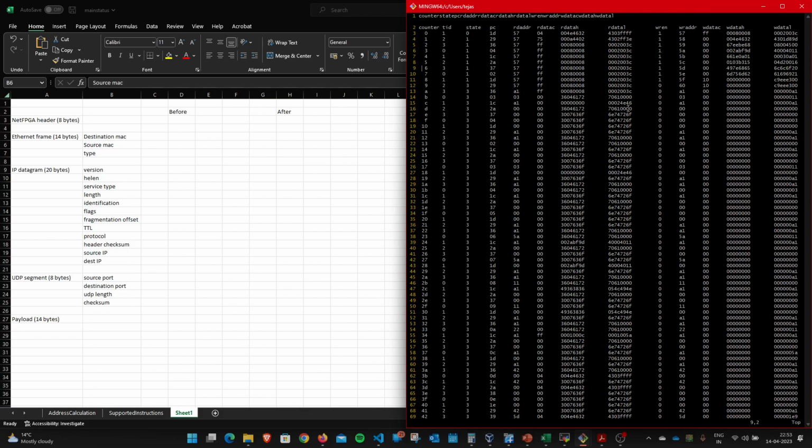What I'm going to do is log each and every piece of data so that we have good clarity on how the input data was, and then what our single-core multi-threaded network processor did to manipulate it. What our assembly wanted to do was force the checksum to 0 and manipulate the payload. So let's go. The first one is FF, which means this is the NetFPGA's 64-bit header.